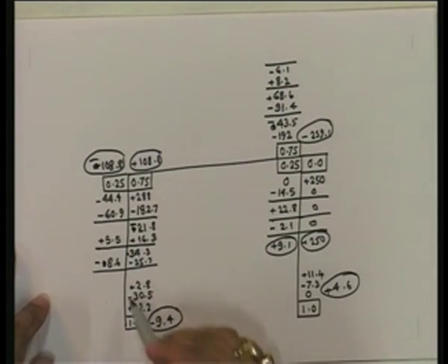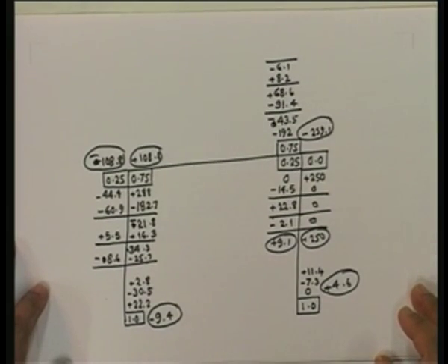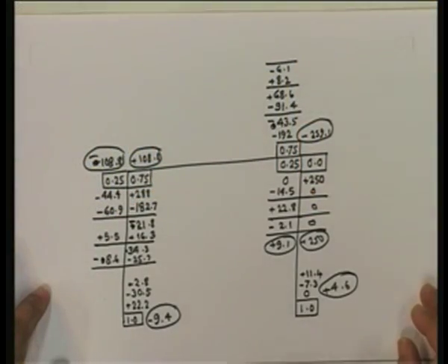When do you stop? You stop when your distribution gets to be less than 1% of the smallest value. Which is the smallest value over here? It's 280, highest value 288. So 1% would be about 2.8. And as soon as your carryover becomes less than 2.8, you stop the entire process. Always end the last step in moment distribution with a distribution.